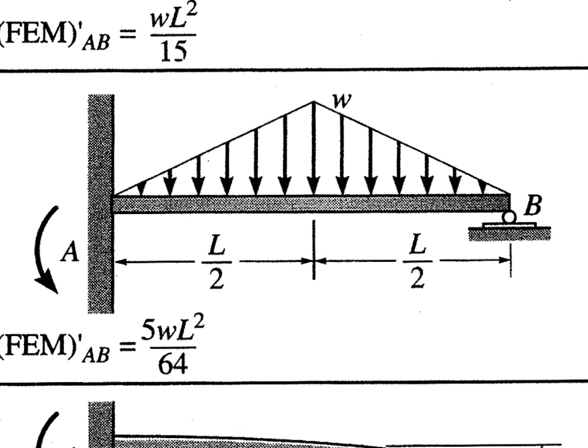Imagine that you have this bridge and it's sitting on this support. But on this end, it's actually embedded in the material. So one end of the bridge is embedded into the desk. The other end of the bridge is just resting on here. What would happen is this desk would prevent it from moving down. It would stop vertical motion, but it would not prevent it from rotating. It could rotate on its own, but it wouldn't be able to slide down. So this cannot provide a reaction moment, whereas this one can.